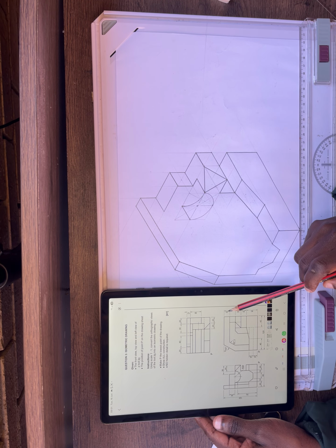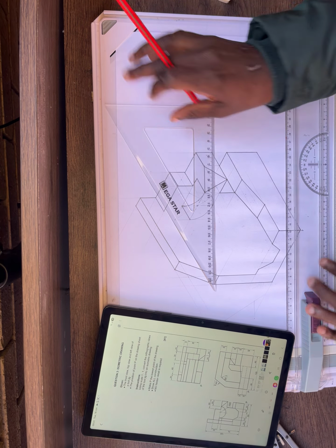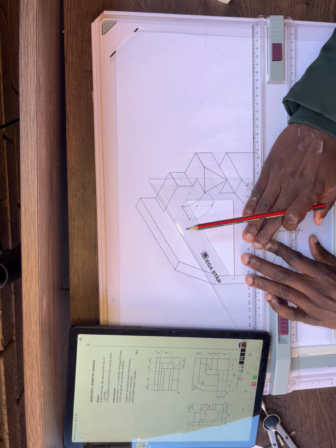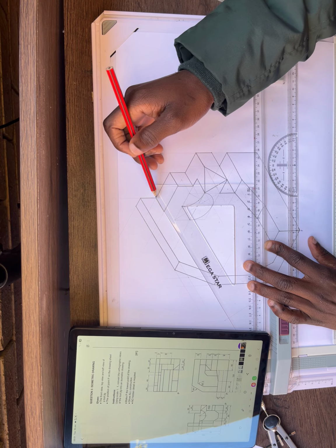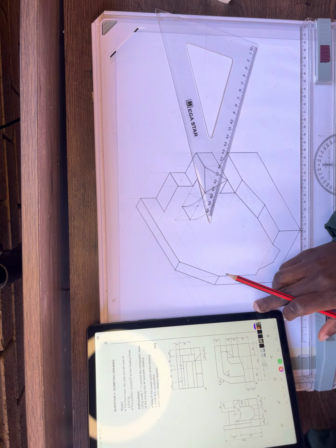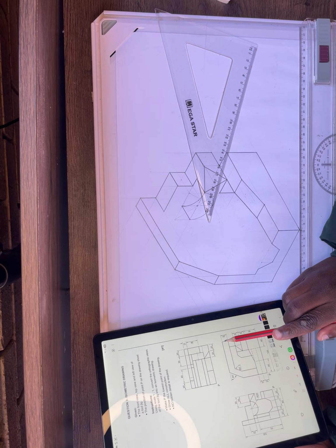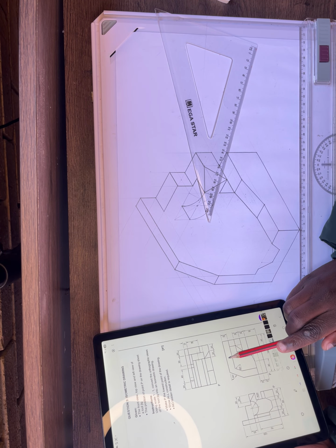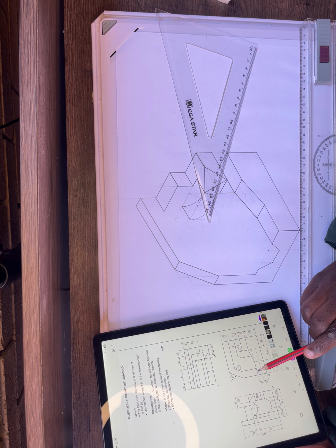Here at the bottom, we first have got this line. So what I'm going to do, I'm just going to do the very same thing that I did on top. I'm gonna draw a construction line from here all the way to this side. And then what is the thickness from here to here? If here is 20, which means everything here must be what? 20. All right, therefore it's telling me that from here all the way to here is given as 20.